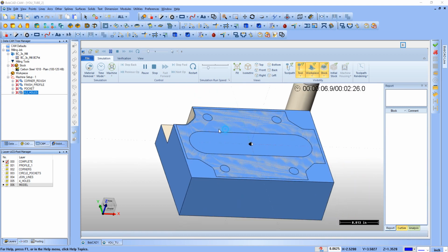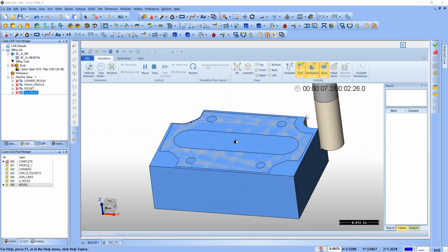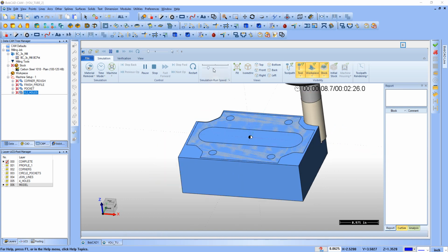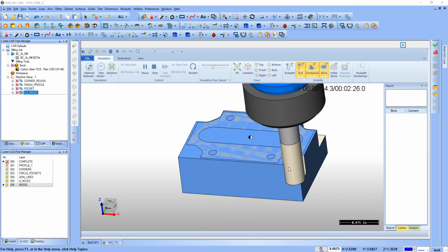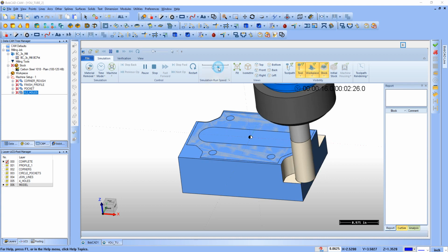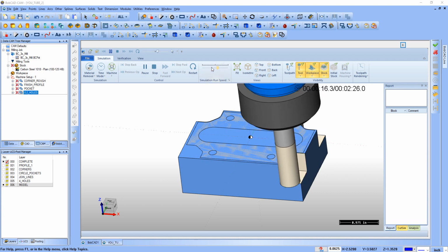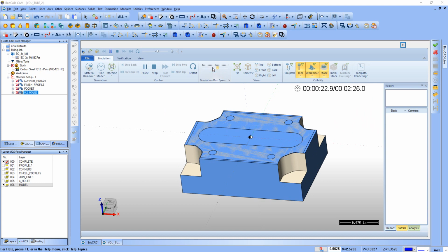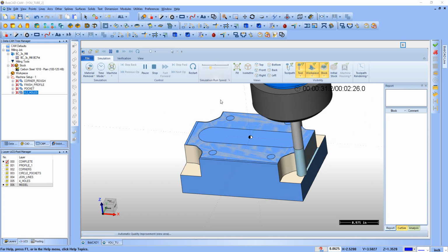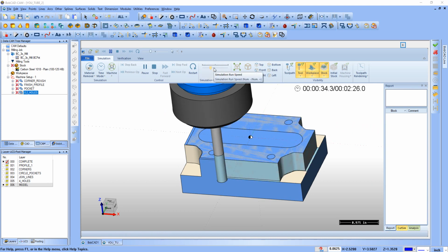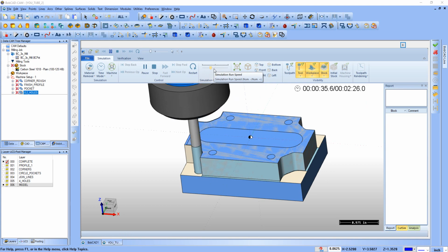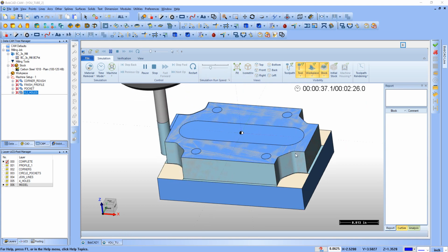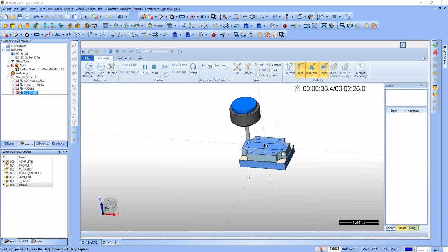But again, you see that side rough out did 3 passes. Because obviously if it came in here and just did 1 pass to the finished number, it wouldn't have cleaned up the whole corner. Let me pick up the speed a little bit. It's kind of touchy trying to adjust the speed, but as you can see, those corners cleaned up because I went down to the 1/4 inch tool.